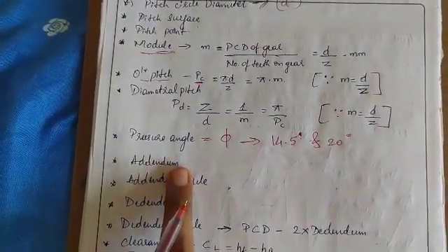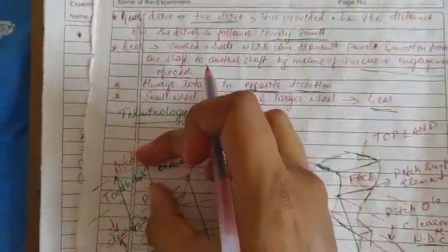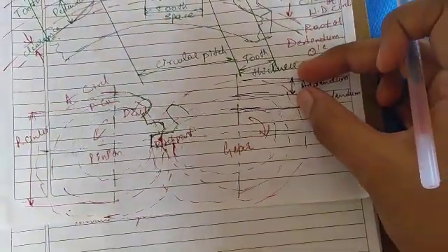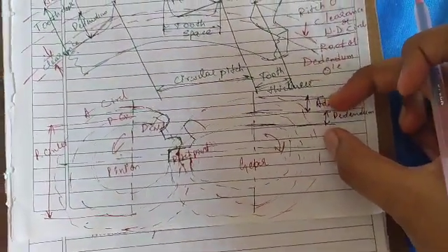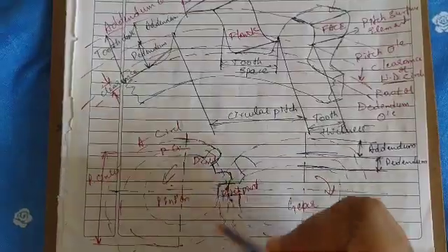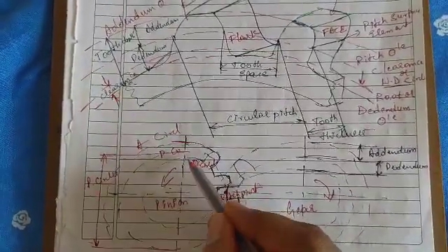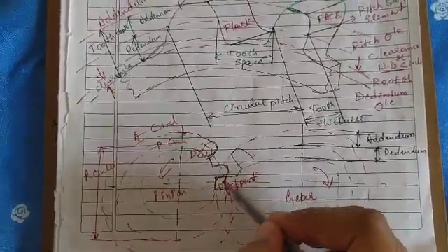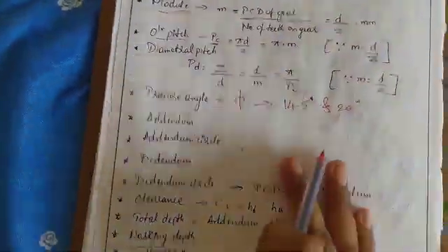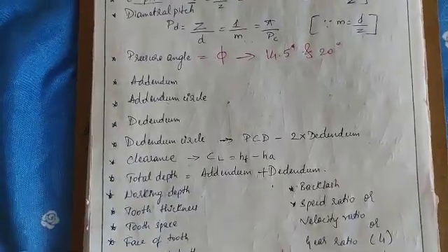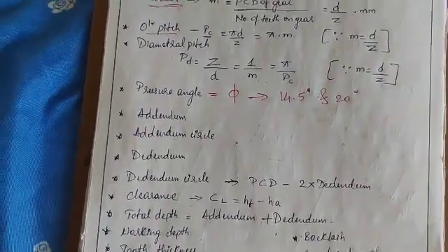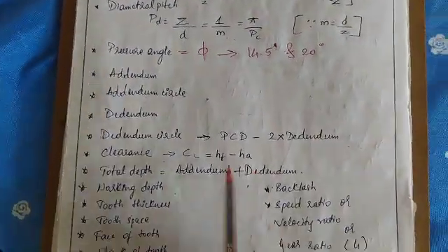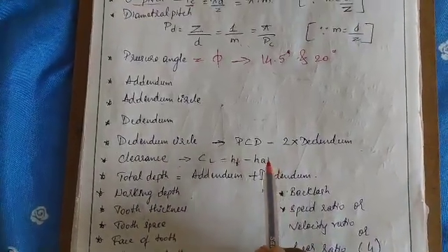And the addendum is the radial distance of the gear tooth from the pitch circle to the top. In the circle diagram, above the pitch circle is the addendum circle, and below it the dedendum circle. In between these two is the pitch circle, where the mating of the two gears happens, that point being the pitch point. And the clearance is the radial height difference between the addendum and the dedendum of the teeth.